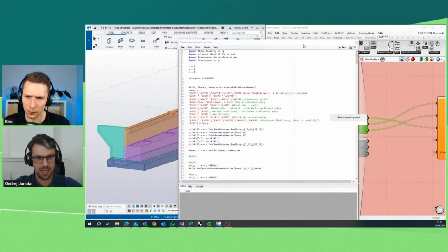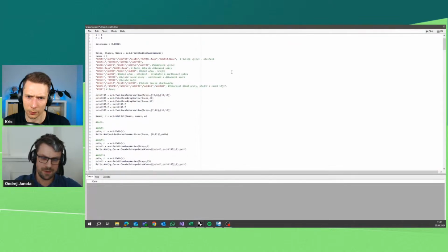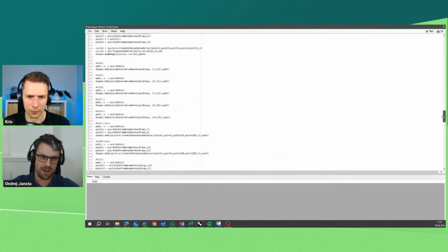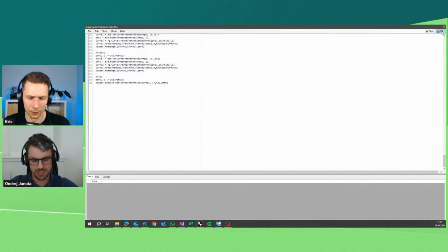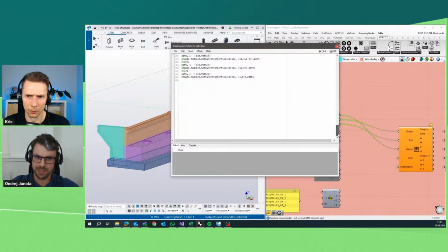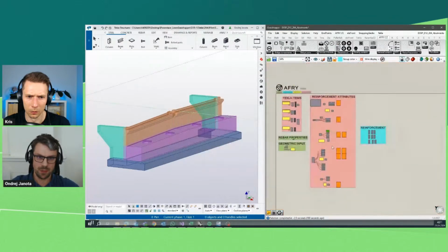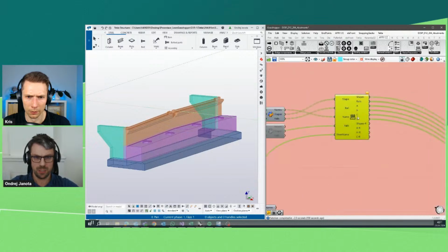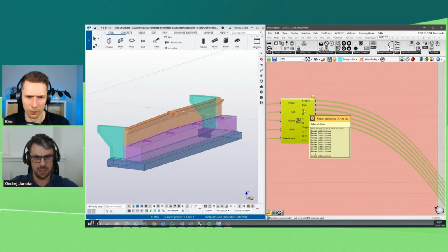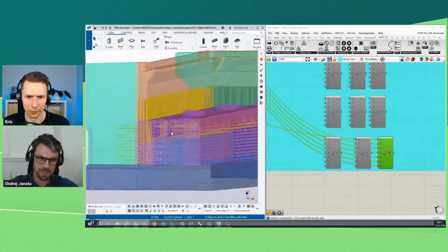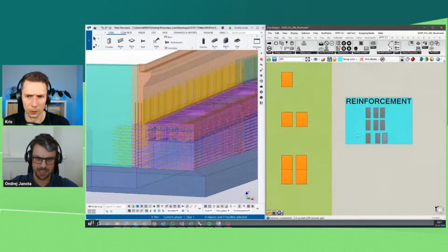What is, I think, also beneficial in this workflow is that how the geometry is defined is up to the user. Generally, there are 3 ways. First, the basic one: if you don't know Python or Grasshopper as much, you can simply draw the rails and shapes of your reinforcement in Rhino on your structure, and then import it into Grasshopper.